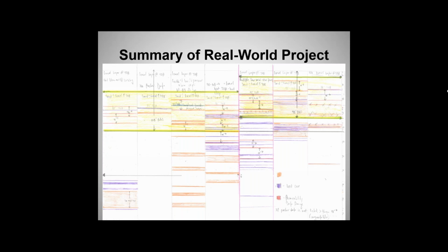The borings represented in these columns extend down to the bottom of the page for each one. You start looking for zones within the core. Where did we lose core? Where did we have core that had clay and weathering, say by these orange sections? We've got a high degree of weathering along the core in those areas. And then how do those correlate with where we lost core?